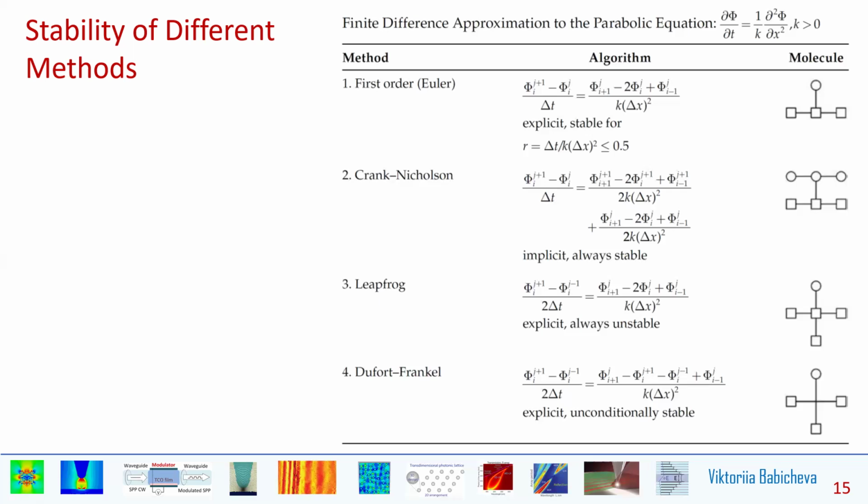The standard von Neumann stability analysis shows that the DuFort-Frankel scheme is unconditionally stable. For such a scheme, the choice of time discretization depends on the variation of the boundary condition and the equation coefficient, for the diffusion time and the material, to compute a solution accurately representing the physical phenomena.